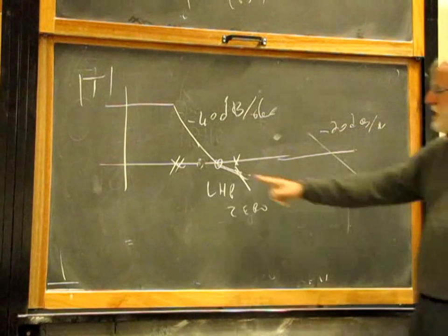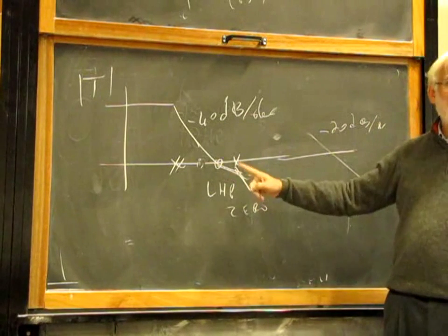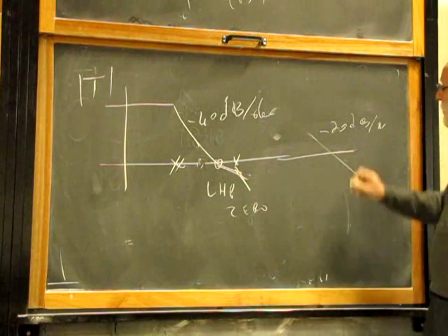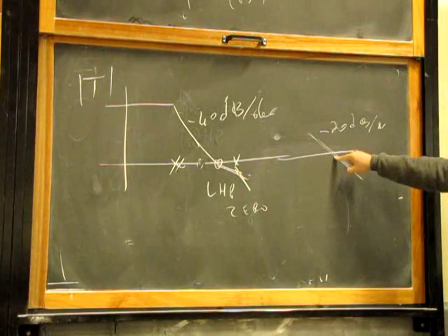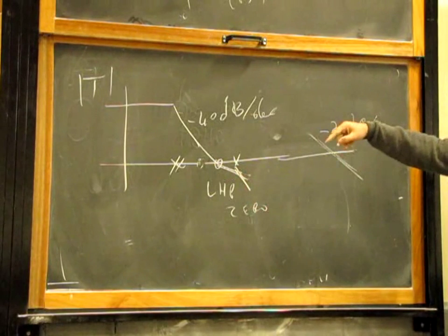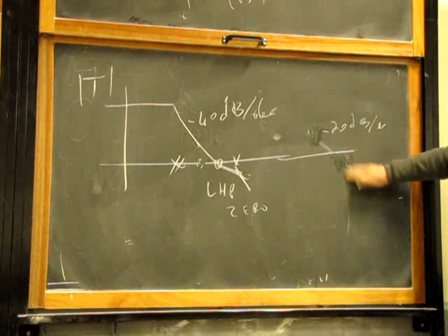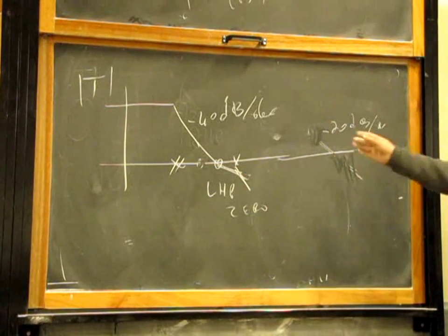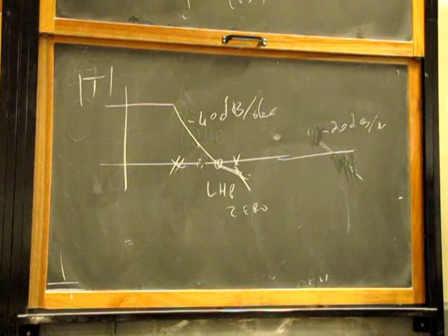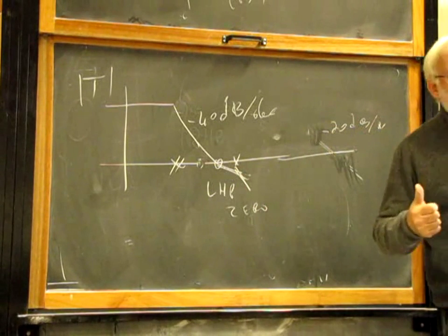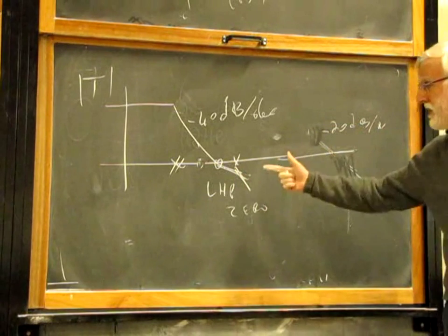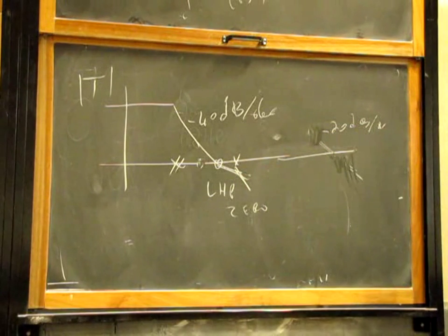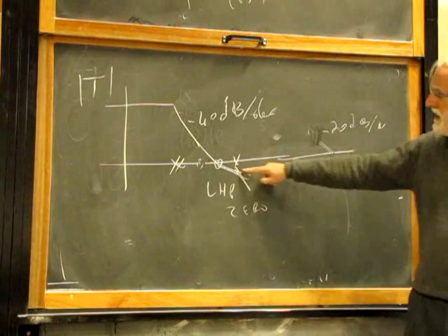If you cross with 40 dB per decade it is unstable, quite sure. If you cross over with negative 20 dB per decade, it could be unstable if you have a right half-plane zero. Gain margin, crossover slope, just forget that. The only good ways are Nyquist or phase margin. Let's look at the phase margin of this system.